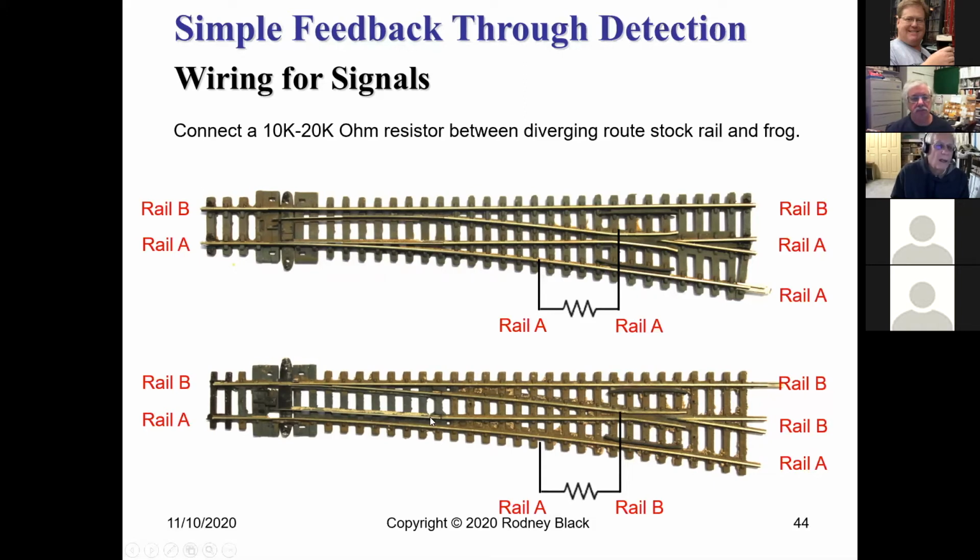This is the way that railroads originally showed detection, or feedback, to knock the signals down. But I think it was the FRA, or whatever the administration was at that time, said it's not safe enough, because they call them shunts, because the shunts may fail. So that's why they went from manual to automatic signaling control.